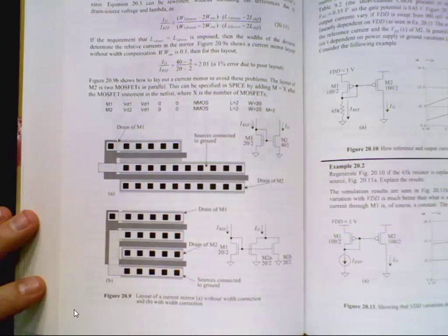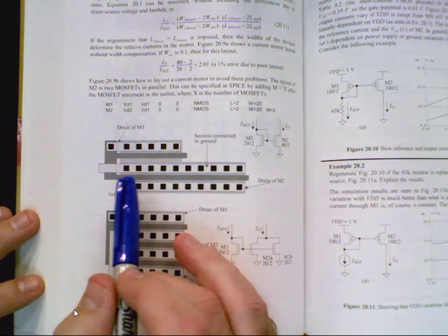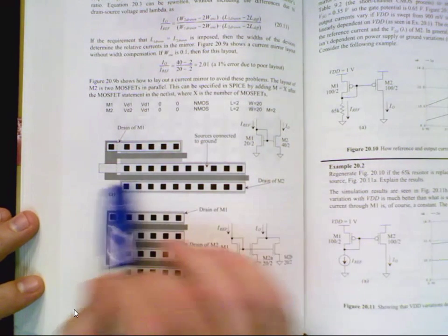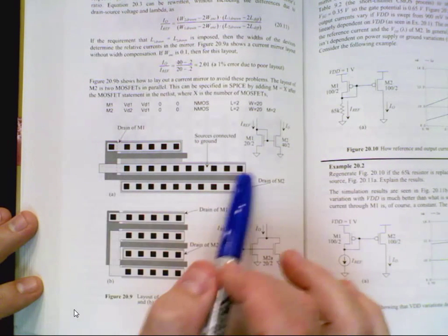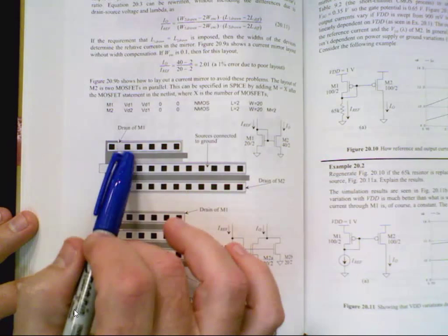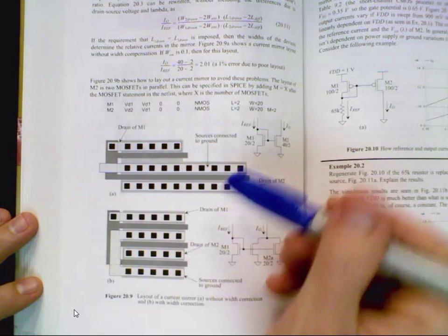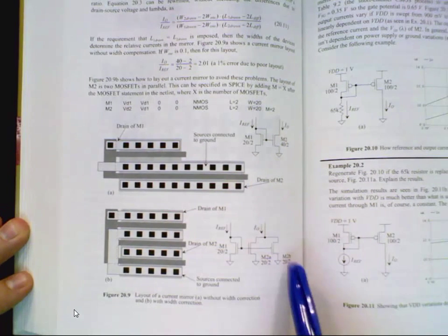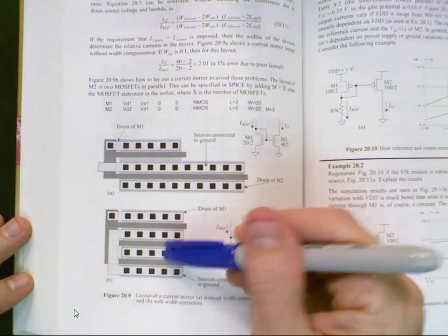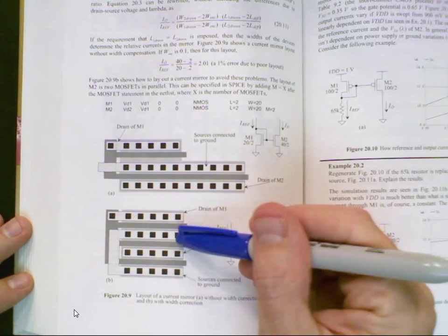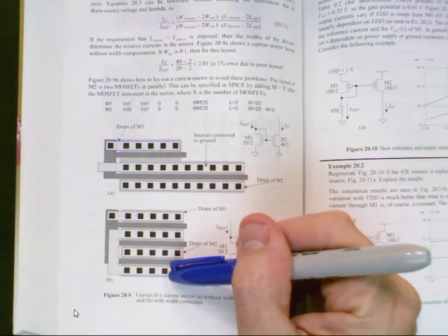Again, we're not doing layout, so if you don't know what this is, I'm not going to test you. If you just double the length like we did here and like we did in the previous example, then the effective W here isn't an integer ratio with this one. Does everybody see that? But if I split this device up into 2, so I use M equal 2 instead of just a 40 by 2, now the devices are exactly the same, and so presumably they will have an integer matching of 2. Did that make sense to anybody?